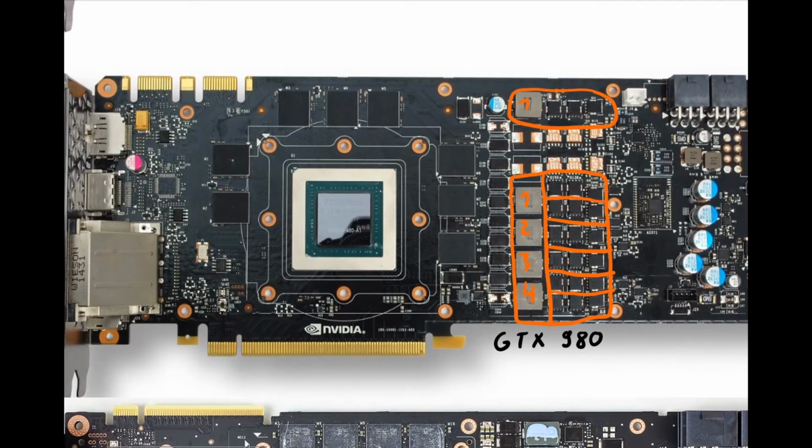So again, then we have also your PWM controller, which I think is an NCP4208 or a newer version of it, which is an 8-phase actually. So you see that there is enough space for 2 more phases. So this could theoretically just be a PCB that can handle 8 phases, but they just cheaped out a bit and didn't put these on.